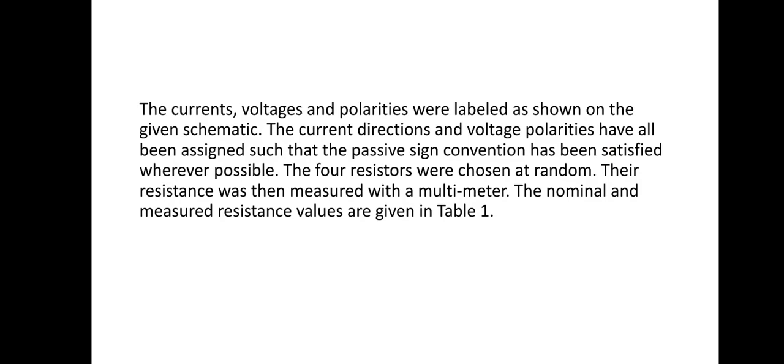The currents, voltages, and polarities were labeled as given. The current directions and voltage polarities have all been assigned, such that the passive sign convention will be satisfied where possible. The four resistors were chosen at random. The resistance was then measured with a multimeter. The nominal and measured resistance values are recorded.